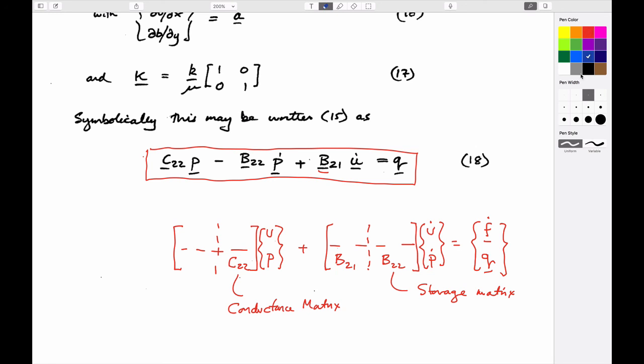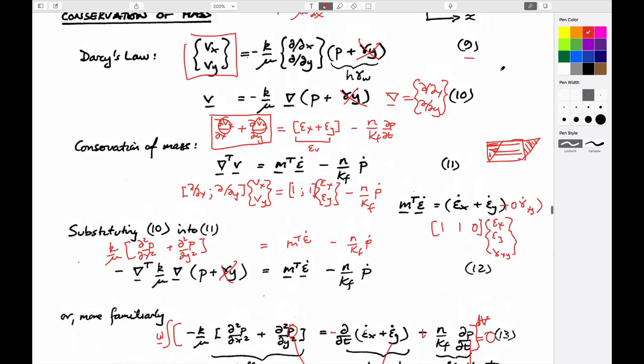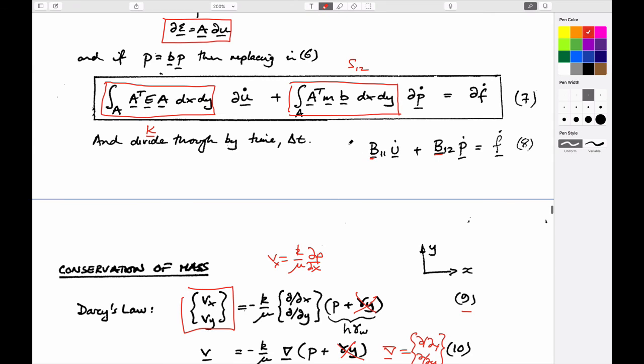So in other words, here, everything without this term in this relationship would just be the flow equation, nothing more than that. If we zip up to this one up here and take this and put it in the right places, then we have something that operates on rates of change of displacements and rates of change of fluid pressures.